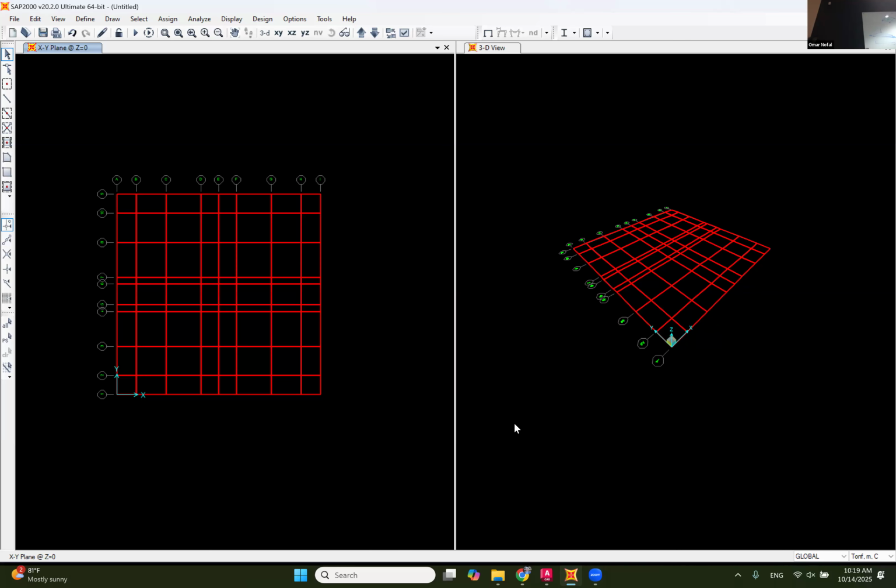Okay? If you try, when you go home, do the same thing and draw a column here, you will find that the slab has a deflection, like not feeling the column, like it's going up and down. So that's really, really important when we do finite element analysis. So let's say that you have a column here. What you should do, we usually drag this point and move it here. There's a way that we can do this on SAP2000.